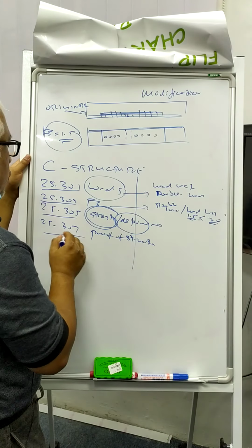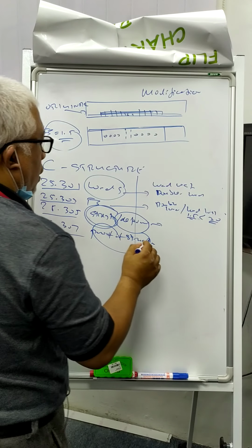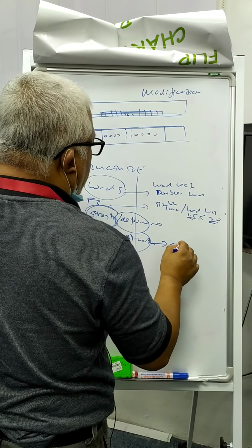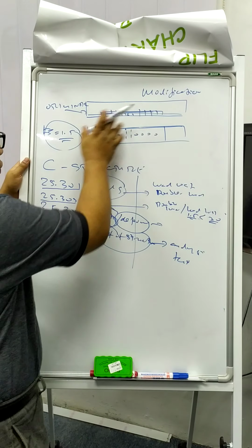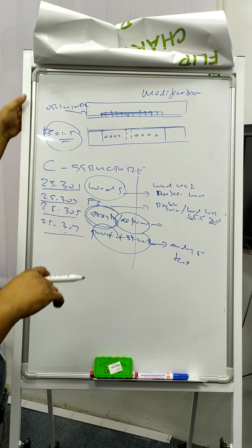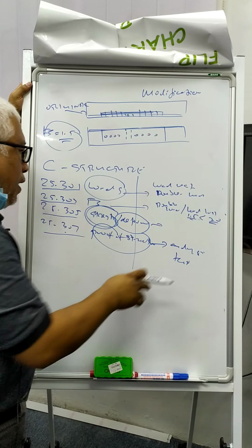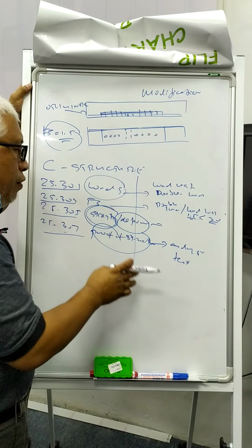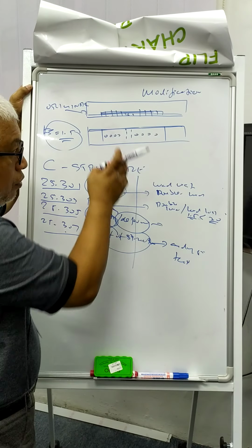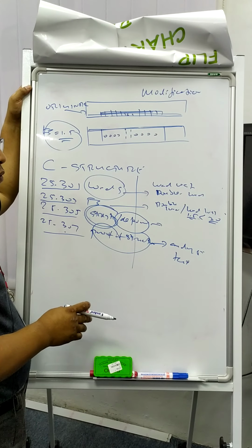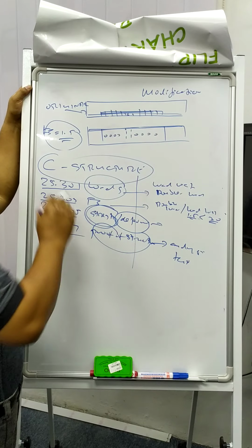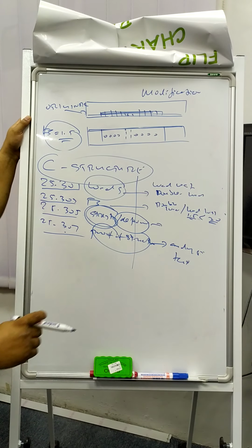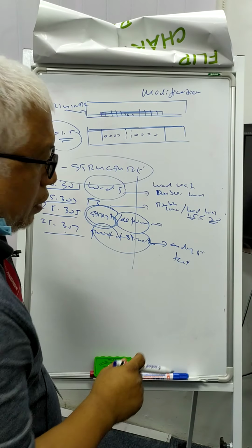And then 307 proof of structure. Either you have to do it by analysis or test. In this situation, for a small piece and maybe just a secondary structure, analysis is enough. If you do a very critical structure, you may end up doing a proof of concept and doing the test. So that is how we satisfy C. And then we move on to D, design and construction.